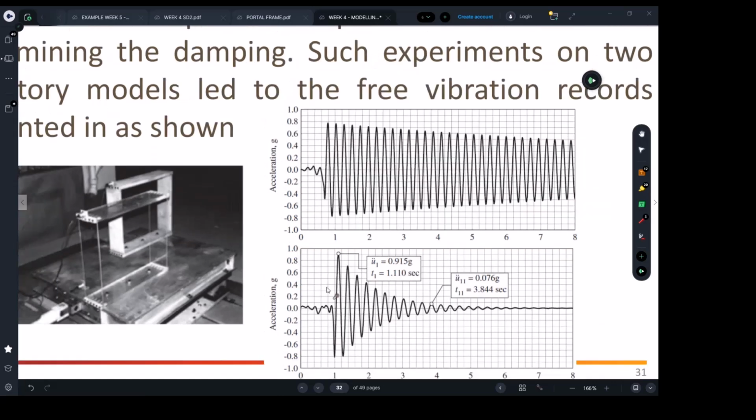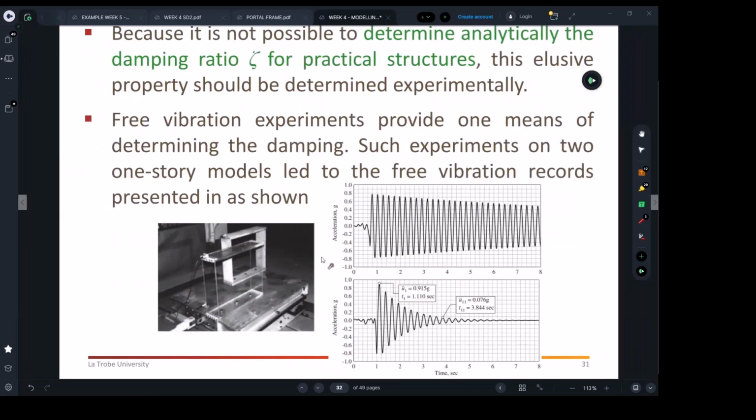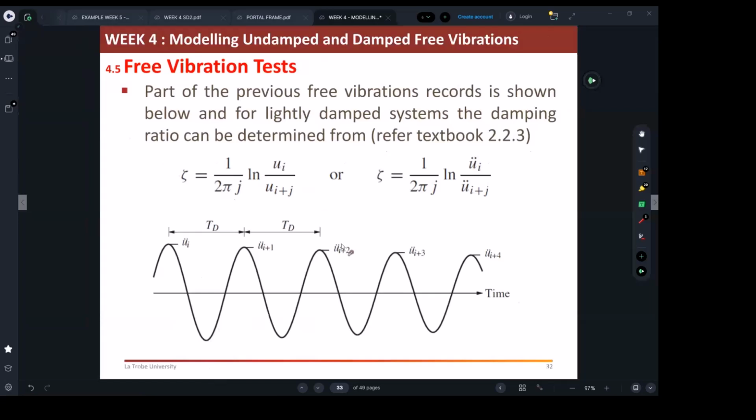You can find the damping frequency, the natural frequency, the natural time period, etc. And again, you should be able to work out backwards the stiffness and the mass and whatever you want. And that's the fun about it. And that will let you make a judgment if that building is good or not.